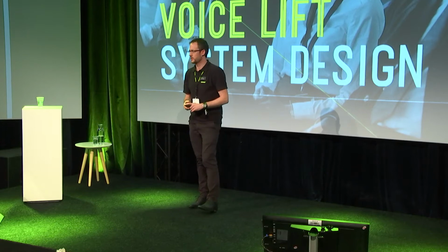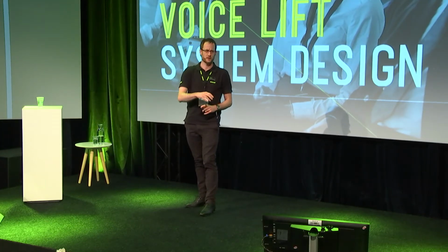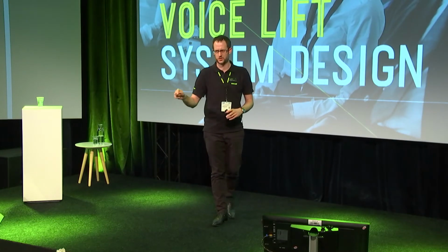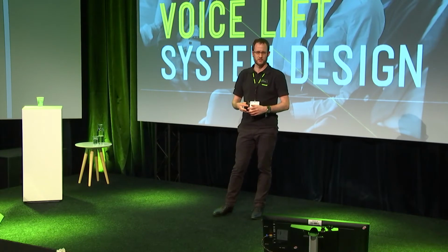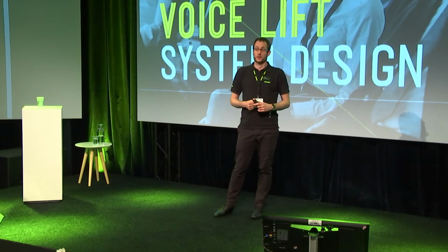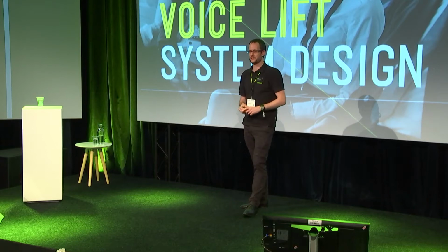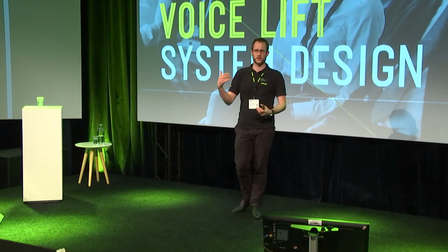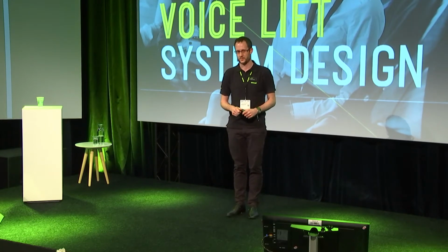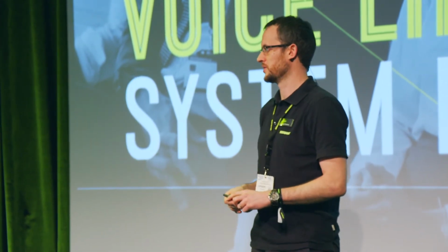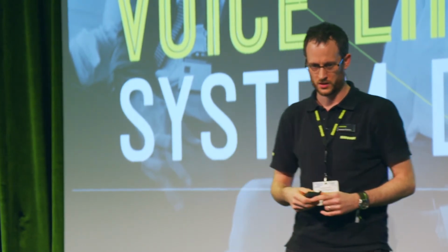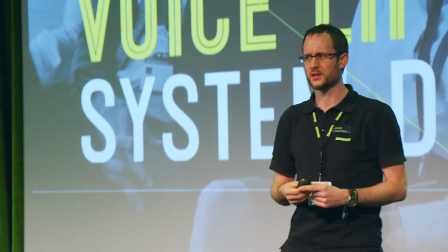But in, let's say, a classroom or a boardroom situation, the need to pass around a microphone or a dedicated push-to-talk system per person can be a little bit of a barrier to fluent conversation. So the idea of a voice lift system is really to compensate for the loss of audio volume over distance. In a larger room, there will be a point at which you can't hear somebody at the other end. So we're going to use a microphone in the ceiling to pick them up and reinforce them to a small level to compensate. It's not making anybody louder, it's just making everybody in the room, regardless of how far apart they are, about the same volume to every listener. Sounds pretty simple, but it's actually quite a complex and complicated thing to try and achieve.